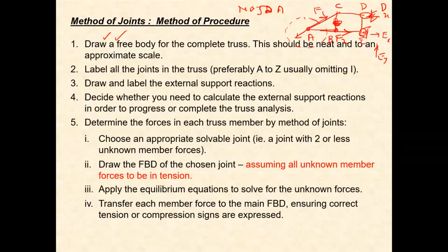And then the free body diagram for that. It has an external force F. This is A. And this force is FAB or FAE, both of them are the same. And this force here is FAC. This free body diagram is solvable because it has one unknown here, two unknowns here, and two useful equations.